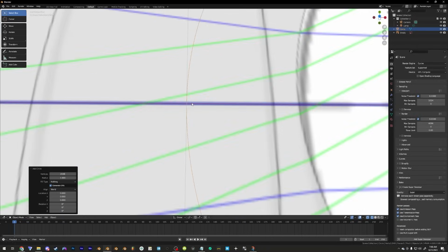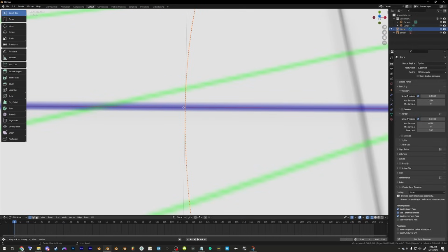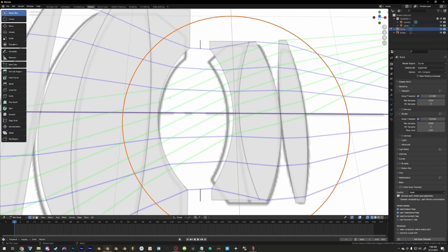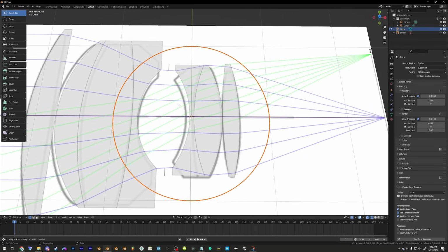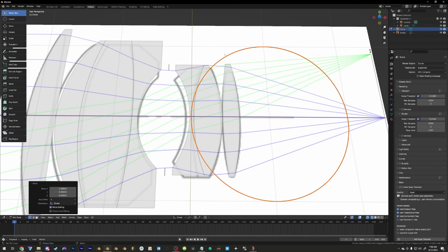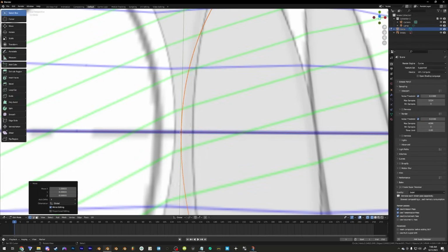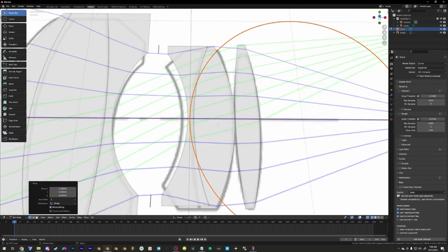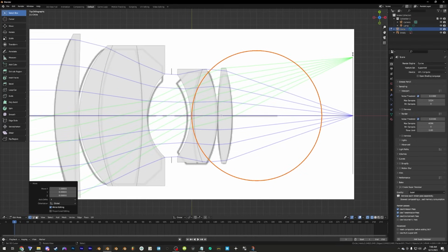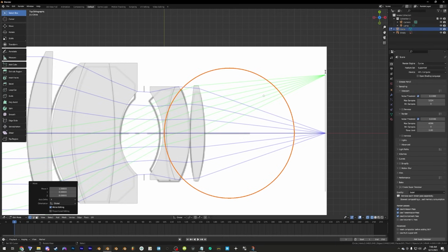And one final crucial detail is that if you go into edit mode, there is one vertice that lines up perfectly with the central axis of this circle. So what we're gonna do is, we're in edit mode right now, so we'll just go G, X, and line up the right or the left side of this circle with the origin of the mesh itself. Then we're gonna go to the orthographic view on our camera, and make sure you're in wireframe view when you do this.